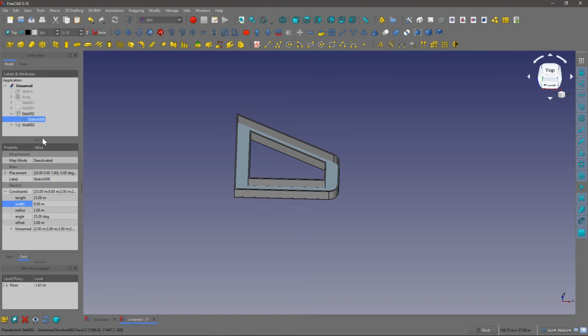Yeah, so sometimes there's some issues, but usually they're not bugs, even though there's definitely some bugs in FreeCAD as well. But it's the way that some geometry is built, especially with sketches. There could be a little gap or some weird constraints or very short segments or things like that that you need to check out.